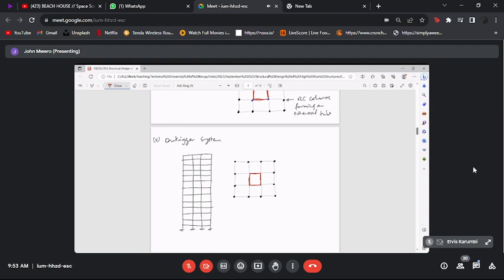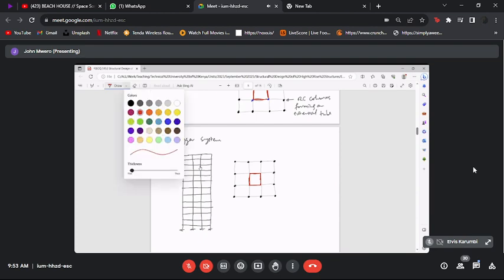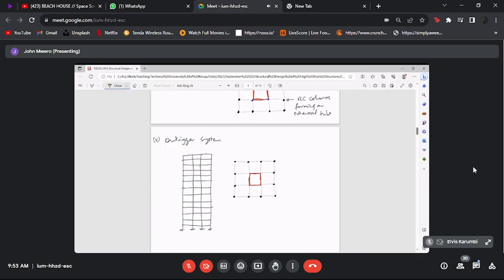Now, if this building, you find that because of the height, it's swaying too much, it is possible to now incorporate as part of the structural system walls, or deep beams, that go from the central core to the external columns in that manner.